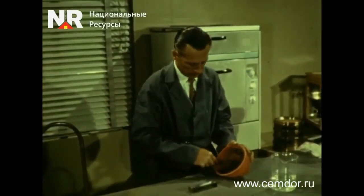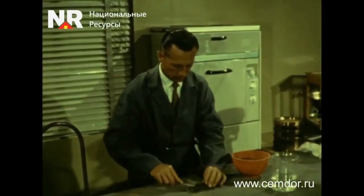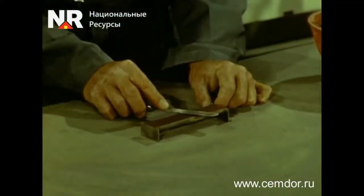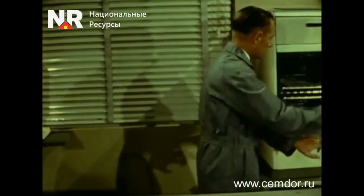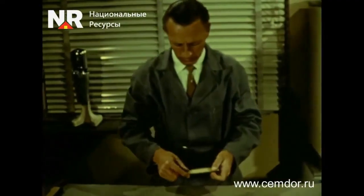Linear shrinkage is the third characteristic of soil. Soil shrinkage refers to its ability to decrease in volume as moisture evaporates from it. The soil is mixed with a certain amount of water, and the resulting mixture is placed into a special mold. Next, the soil is dried to a constant mass, and the amount of shrinkage is determined.